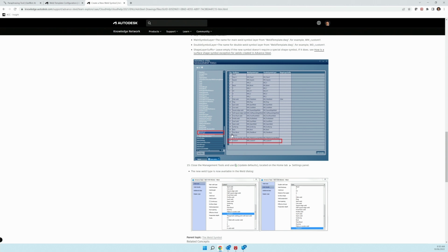However, what I've found with my readjustment, because I rewrote this table to suit my layout or my welding symbols, I basically thought, oh, I don't need a dummy weld, I will remove that. So in my previous video, line 22 happened to be the backing material removed, and when that weld symbol was chosen, the macro must be looking at line 22 of this table and saying, well, that one there, don't show that weld.